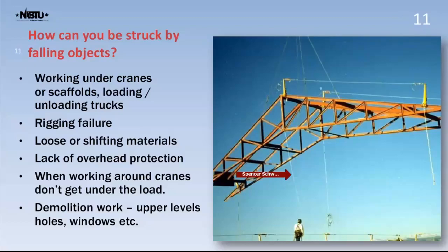They're supposed to use chutes to make sure the stuff doesn't hit workers below, but not everybody knows that. So especially if you're working around a demolition project or a renovation project, you want to make sure that people are aware of where the trash and demolished equipment is going when it's going out the window.